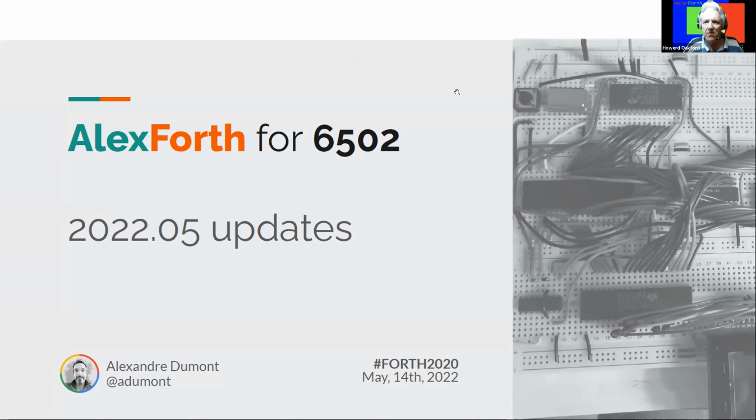Just a thought. Oh, that's interesting. Yeah, I'll try that. A word of caution: you might blow some tracks if that short is too far away and you've got some narrow tracks. So I tend to apply that very close to where I think it is. But most of the time it's just a tiny bit of copper. You can even control the current. Just put an amp through there or whatever. It's not going to blow it, and then go along with your meter and you'll be able to measure the voltage drop, and you go, aha, here it is.